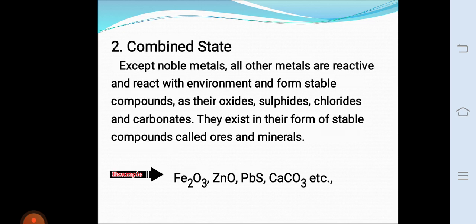How and why does corrosion occur? The metals are extracted from these compounds, known as ores. During the extraction, these ores are reduced to their metallic states. In the pure metallic state, the metals are unstable as they are considered to be in an excited state, that is, a higher energy state. Therefore, as soon as the metals are extracted from their ores, the reverse process begins and forms metal compounds which are thermodynamically stable, that is, a lower energy state.